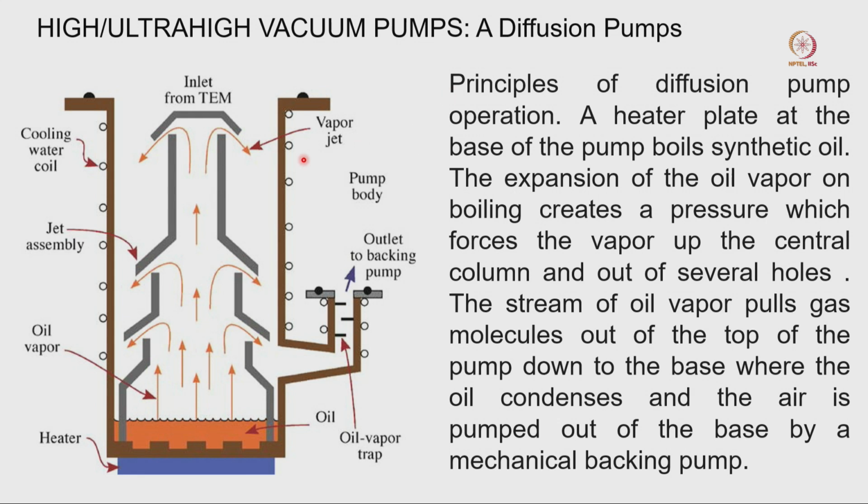Most of the time in all these cases we are using some synthetic oil. And now the outer part of this pump, we have a cooling water coil, where the cold water will go through this pump and it will maintain a very low temperature of this outer part of the pump. That will help us to condense the air molecules and water molecules, and that is the reason we are using this kind of cold water.